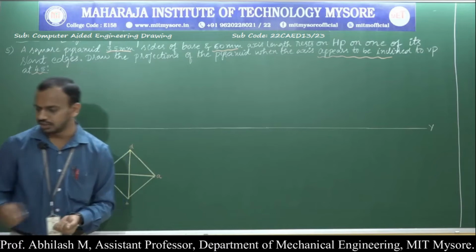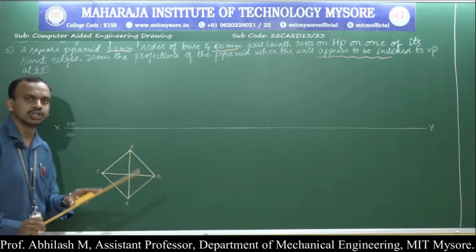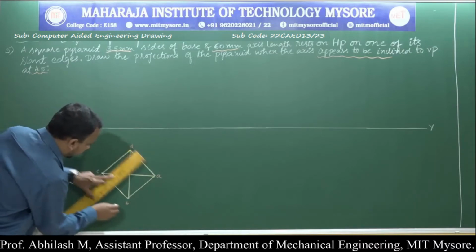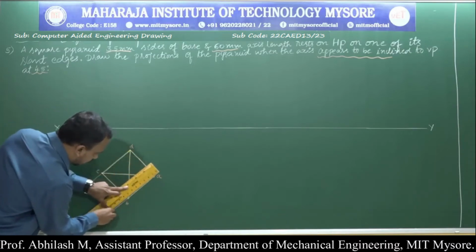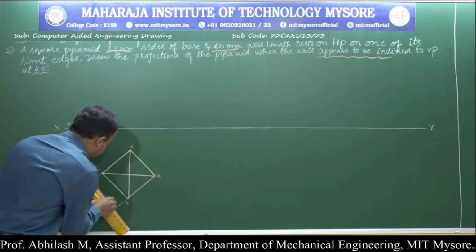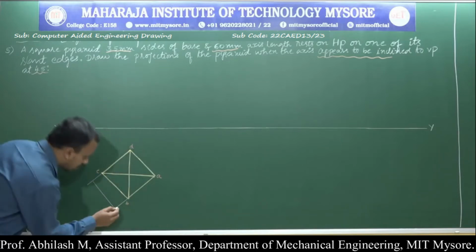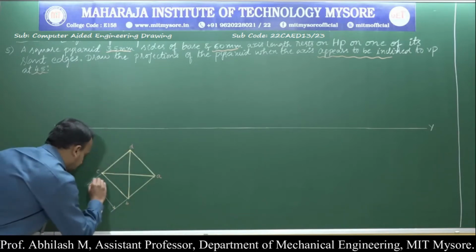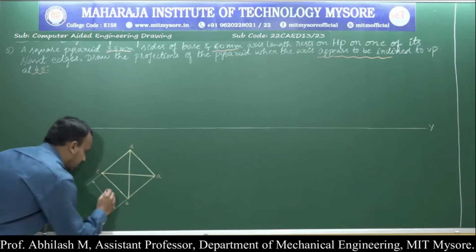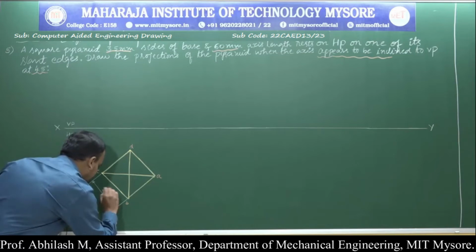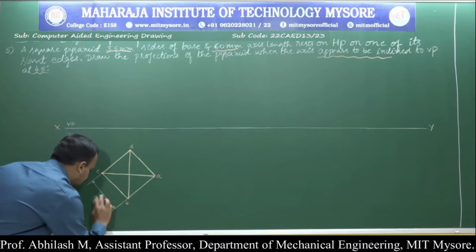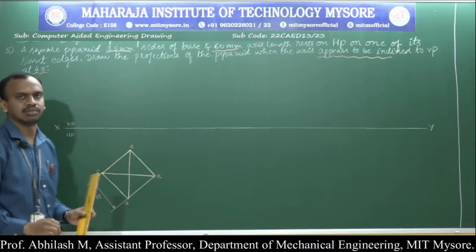So what is the final thing that we are supposed to do in this particular position? Show the dimension of any one of the sides in order to complete this particular position. Take any one of the sides, highlight that. These are all the fundamentals that you have already learnt. So draw an arrow, a filled arrow basically, and call the side by the given dimension. So here the given dimension is 35 millimeter. So draw it as 35 millimeter.